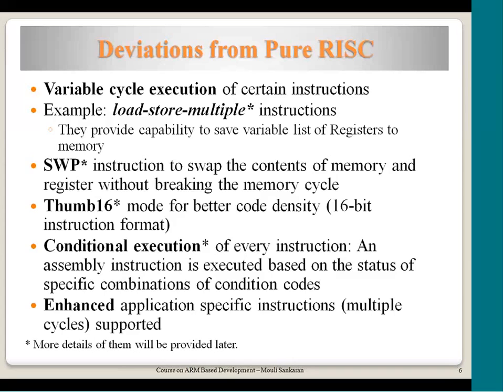One example is the load store multiple instruction, which helps you store multiple register contents into memory, or recover multiple 32-bit values from the memory into registers. So a single instruction takes more cycles based on the number of registers in it.